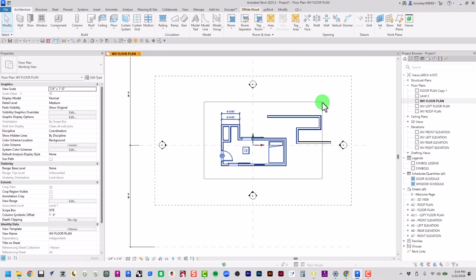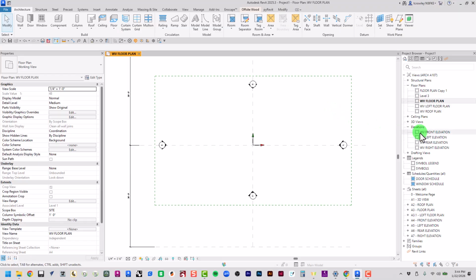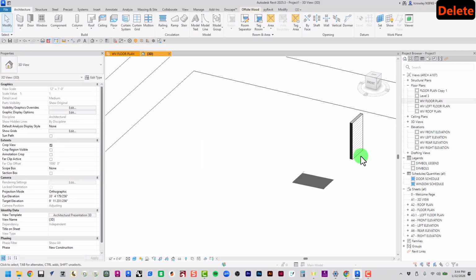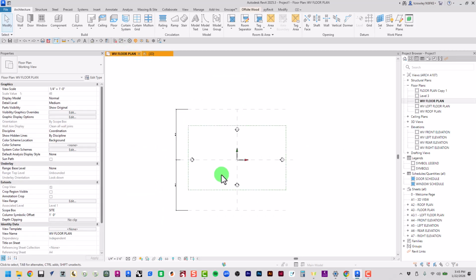Where is it here in this floor plan, right? It doesn't exist in this floor plan. This floor plan is cutting at 4 feet, right, relative to level 1, right? So it's way up here, floating like a ghost, and I'm only looking at this level and looking down. So let's make sure everything is deleted. Don't delete these levels. You want to keep those.